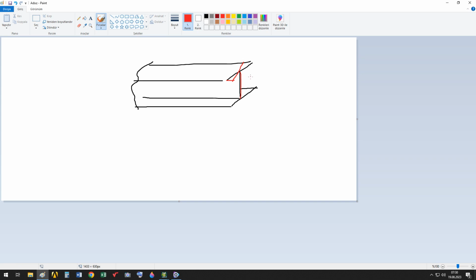As you see, the bending moment at the top flange is so. And now think that the bending moment at the bottom flange is so. So the resulting bending moment is zero, caused from warping of the cross section.